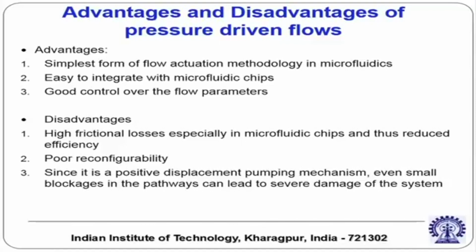So high frictional losses especially in microfluidic chips and thus reduced efficiency. So we have seen that even for a fully developed laminar flow through a circular tube, for a given flow rate the head loss is inversely proportional to the fourth power of the hydraulic diameter.